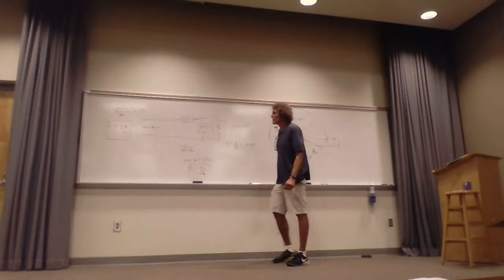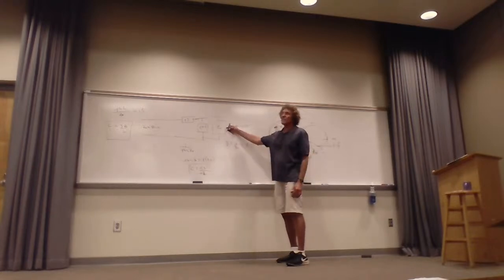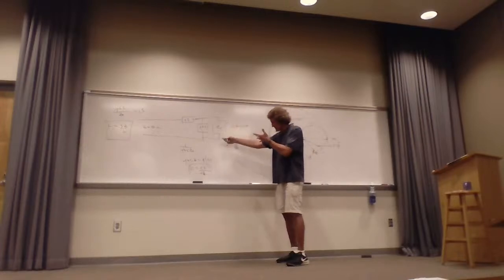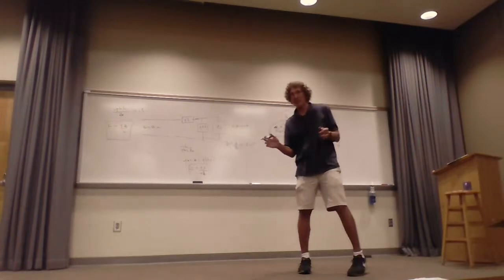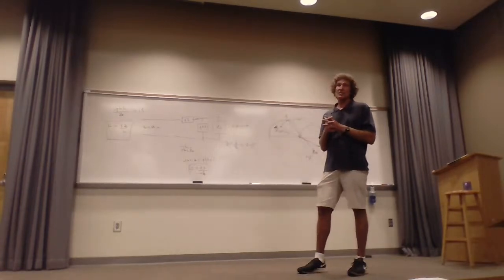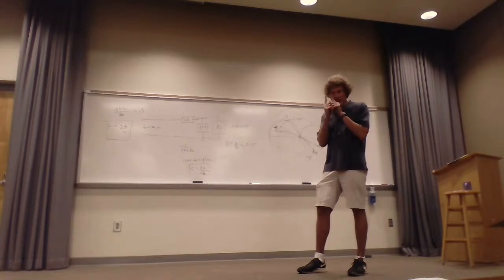Now, without getting into a whole lot of it, if your load impedance has the same ratio of change, the real and imaginary part, as the line, then you don't have to worry. But frankly, most of the time, any kind of impedance matching works for one and only one frequency in a very narrow band about that frequency. All right, so keep that in mind. Wideband radar stuff and all that, you can't use this. There's other methods you have to use, and that comes later.